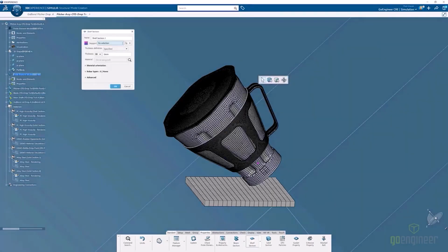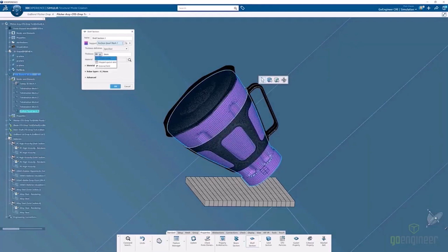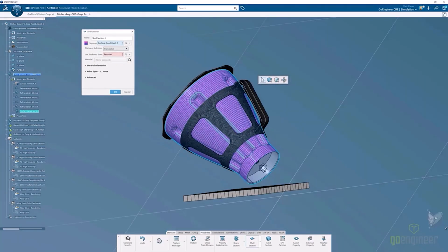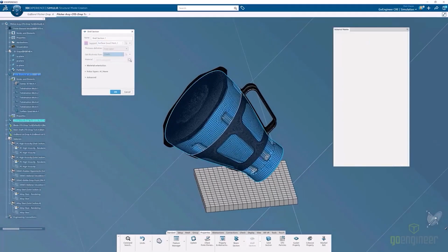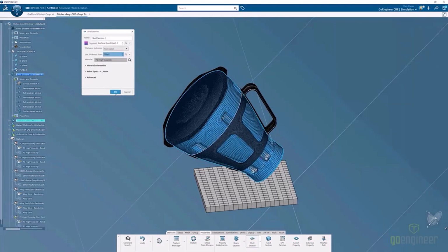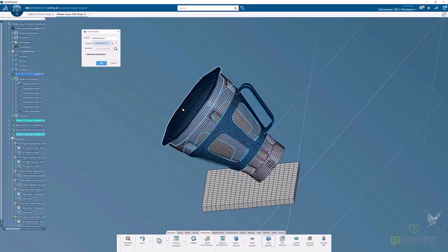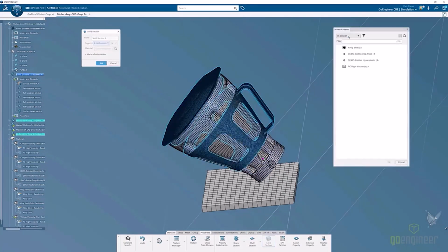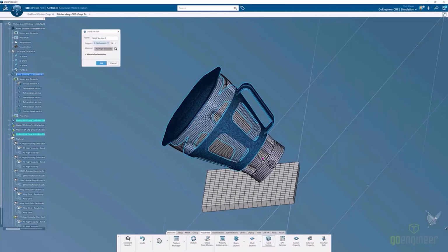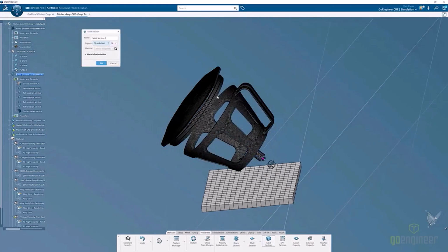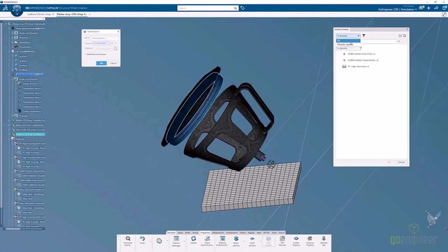We're going to go ahead and look at adding the materials into the model. So again, he's going to add these into the solid section, so the appropriate polycarbonate for the pitcher, the appropriate polycarbonate for the lid, the silicone for the gasket, and the nylon for the handle itself. So he's adding those all into the model. So we have those materials assigned.